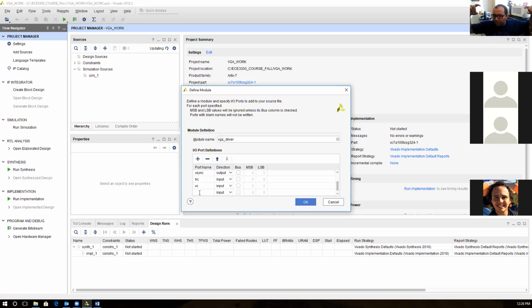If you remember from the VGA, there was a part that's going to be dark, and we are waiting for the signal to go from high to low, right? And then there is a place in the middle, and this place in the middle we call the display zone, which is the zone where we can receive any pixel and it will be recognized by the human visual system, right?